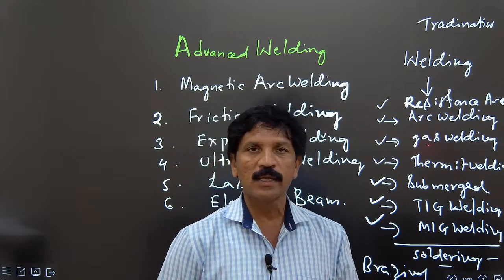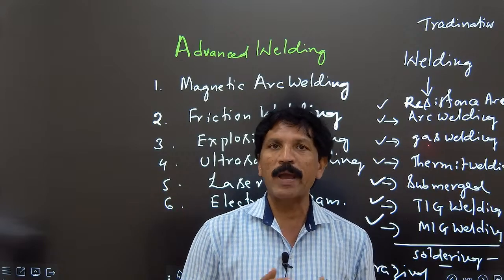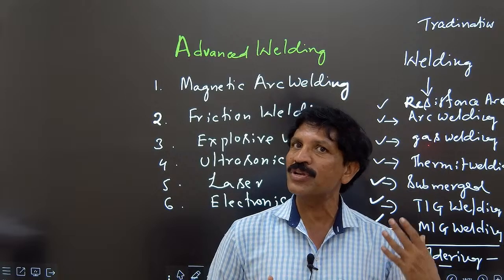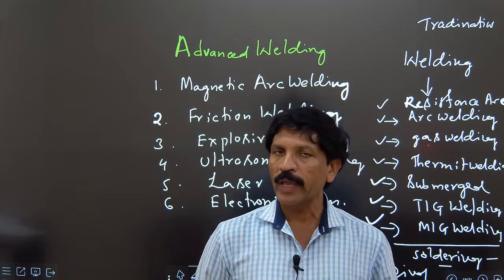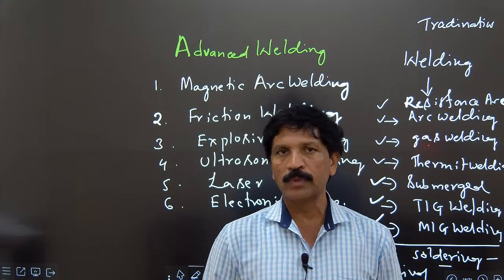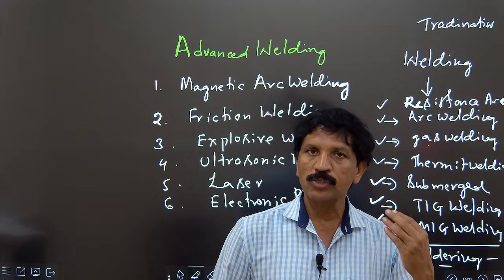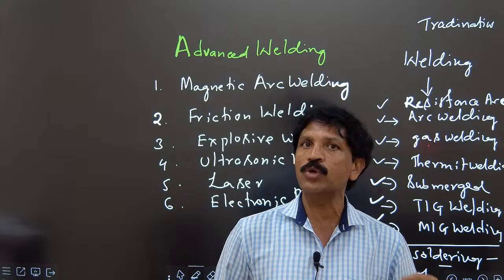This is because it is totally manual work, not automatic work. Manual errors include the selection criteria of the electrode, the holding of the electrode, the traveling of the electrode, and the kind of cooling. Similarly, the percentage composition of the electrode material may not be in the proper way.